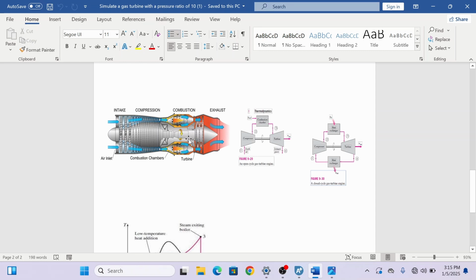This large volume of gases carrying a large amount of heat is used to move the three-stage turbine blades, and after transferring their energy and rotating the blades of the gas turbine, these gases go into the environment. This is simply a gas turbine. After this gas turbine, at the exhaust, we place an HRSG system, and you can see this is the open cycle for a gas turbine. So we are following this open cycle.